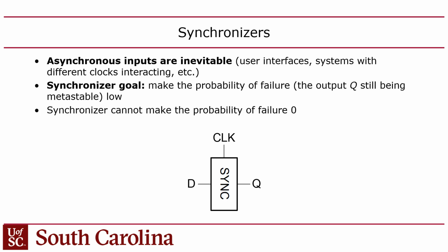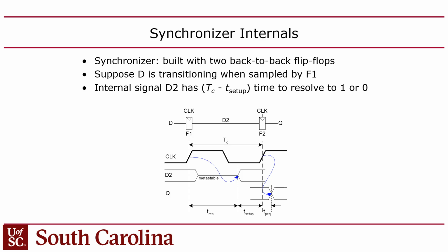Okay, so why are we talking about this? Because there's this thing called synchronizers. A synchronizer is a way where we can try to protect ourselves against metastability on input pins. It doesn't always work. But the idea is that if you protect all of your inputs with another flip-flop in series, right? So instead of connecting your input pin directly to a flip-flop, put another flip-flop in.